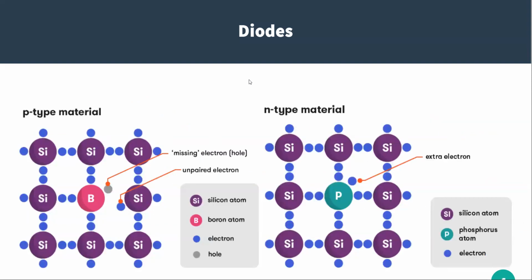Okay, we talked about P-type and N-type material and things being made out of silicon. Silicon itself is a crystalline structure, has 4 valence electrons, and it is essentially an insulator, even though it's classed as a semiconductor. To make semiconductor devices work, we have to make P-type or N-type material out of silicon or germanium. In this case, we're going to make a P-type material.